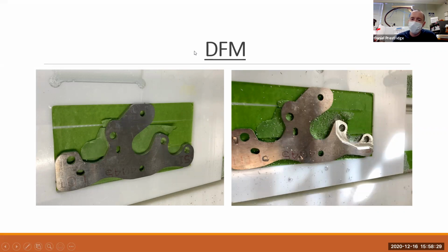It was done that way because they used this thing called topology optimization, which minimizes the amount of material you have, and it still generally maintains the integrity of the part just based on the loads that you apply to it. So it's a really cool way to go about things, but it can be pretty awful for the person who's making it.